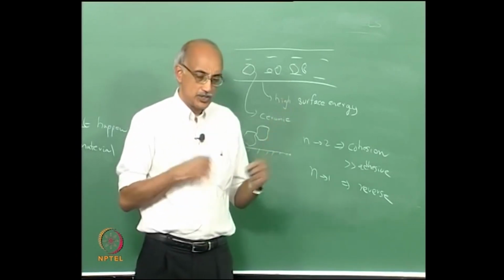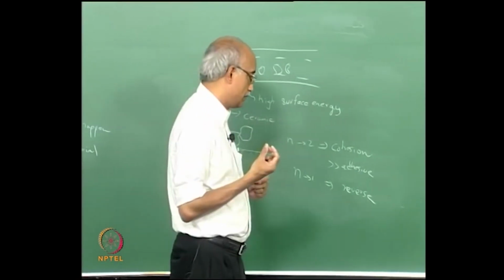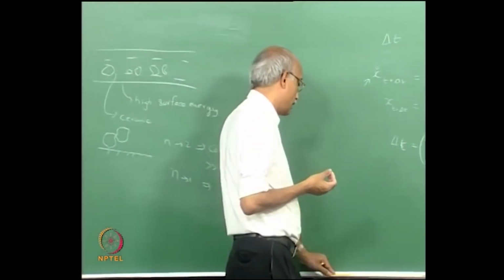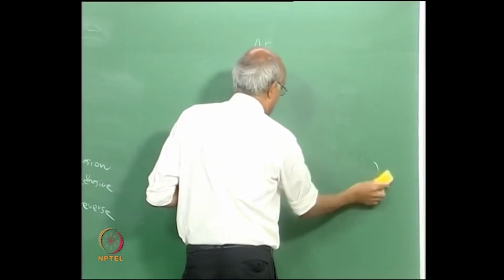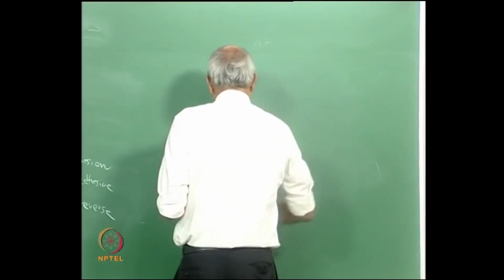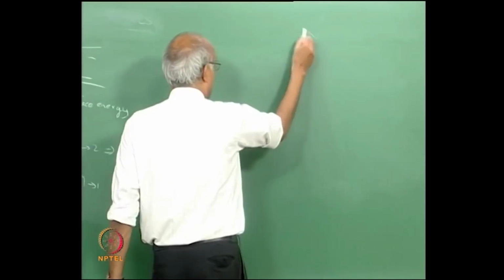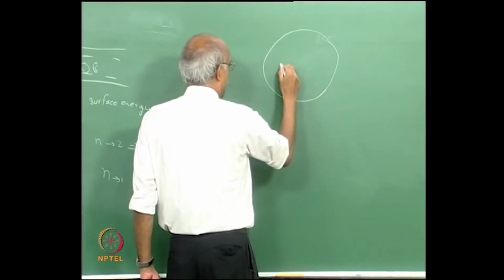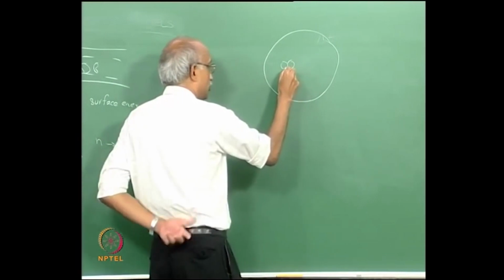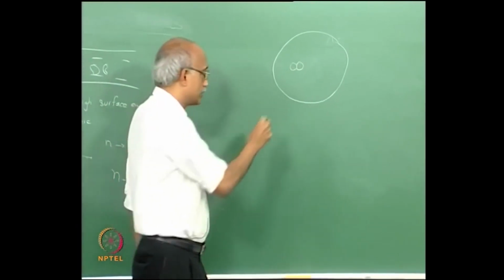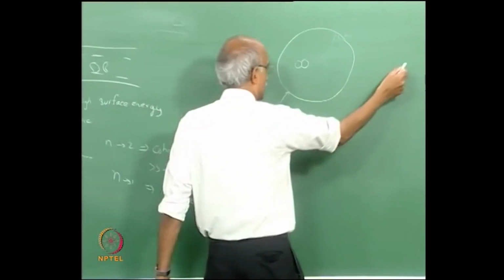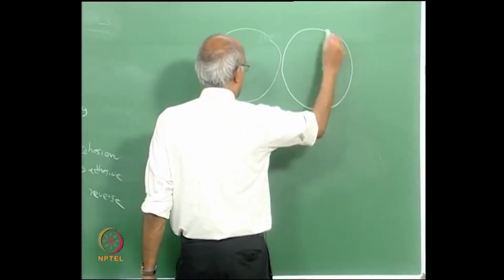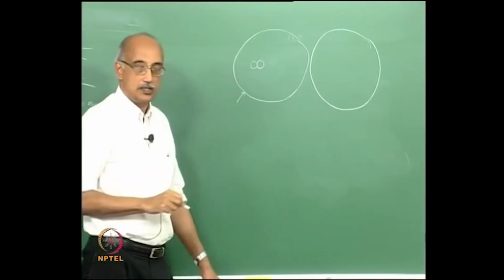Now, the issue that I mentioned earlier about when you have, for example, a product that needs to have different characteristics of interparticle adhesion. For example, if you have a tablet and you have particles in the tablet, you want these two to stick, but you do not want this surface to be sticky, so that when you have an adjacent tablet, you want to minimize sticking between them.